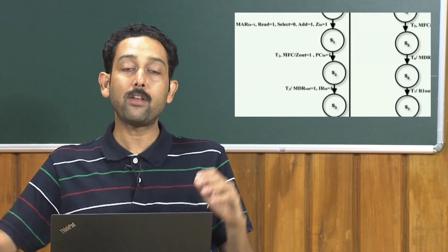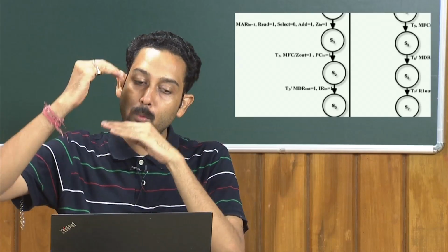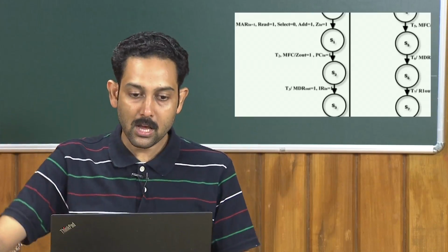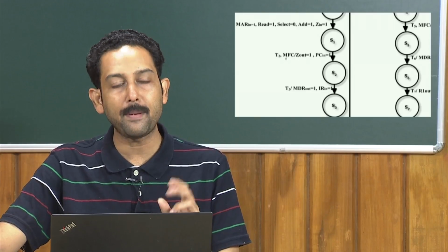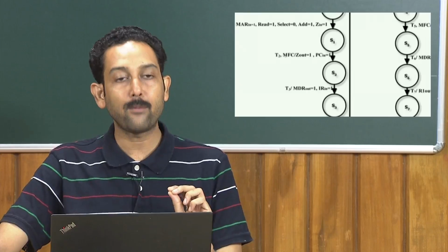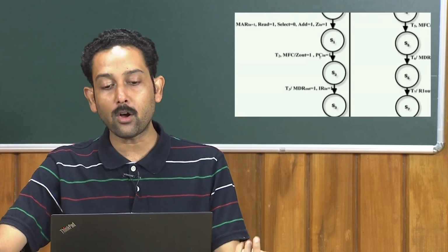Only here, whenever you have given a read signal to the memory, you have to wait till the memory says that I am ready. So in that case the transition from this state to this state will depend on two inputs, one is the state and one is the external signal, and then you generate the corresponding signals.